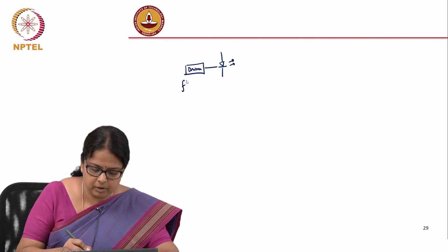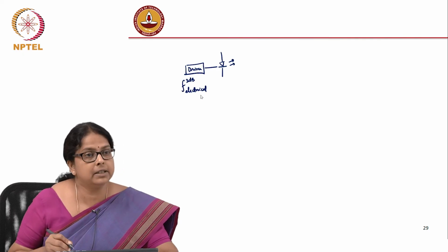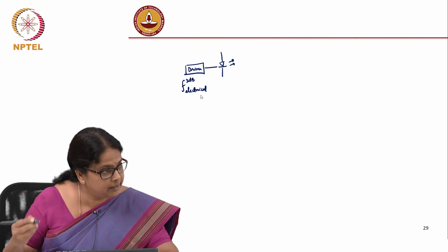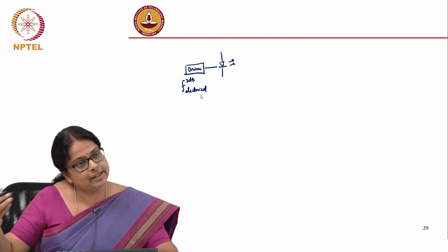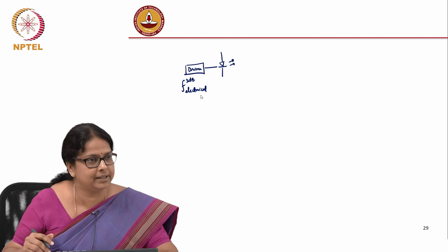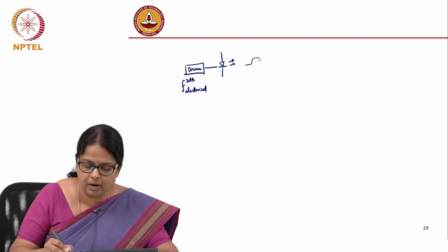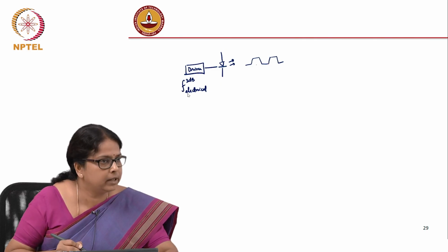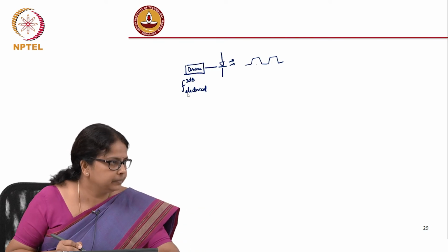So you are worried about 3 dB electrical. But you know that if I have a specific 3 dB electrical, optically it is anyway √3 times more than that. You will have to worry about it only if it were less than the electrical bandwidth, but this is anyway more, which means that the light coming out, on and off, will definitely respond to what I give at the input of my driver circuit.